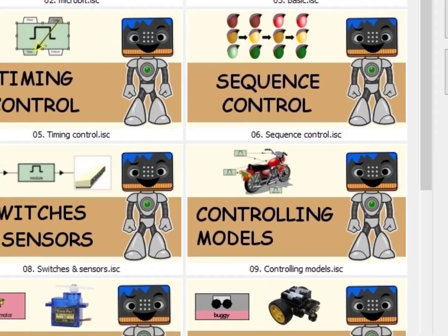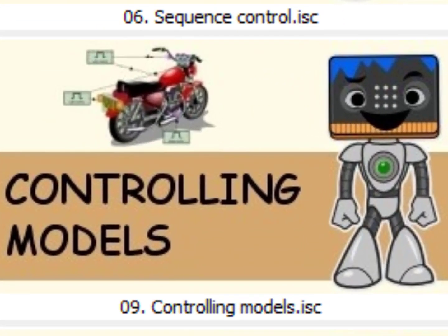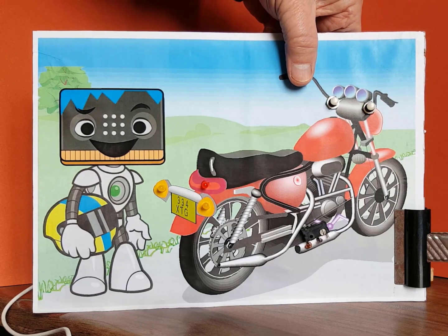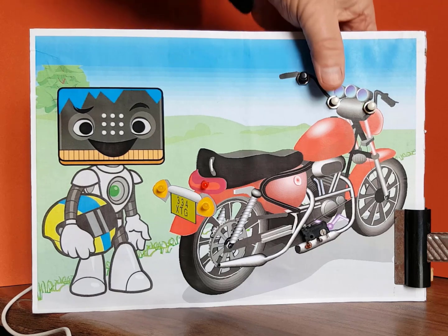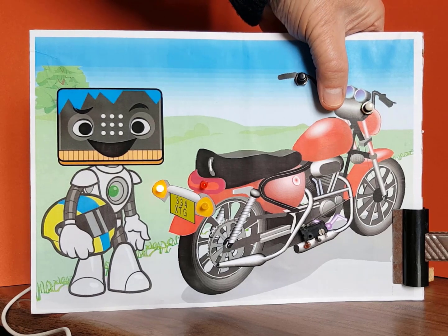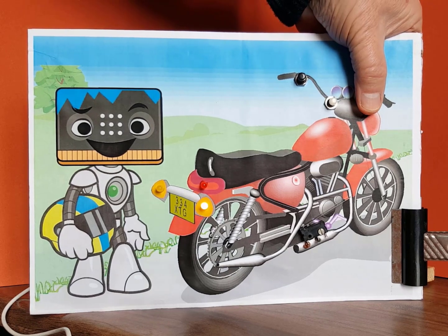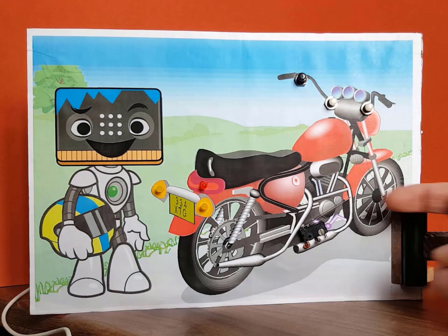This tutorial shows how a simple model containing electrical sensors and devices may be connected to and controlled by a microbit. In this example, we have a push button controlling a buzzer, another button for controlling an LED for turning left, one for turning right, and a switch for controlling a brake light.